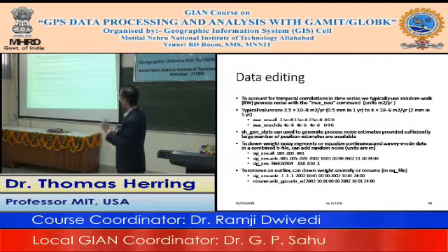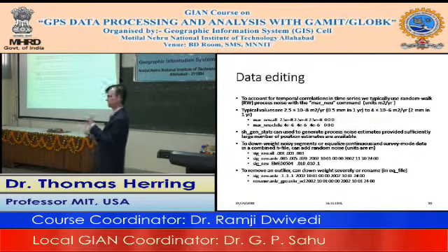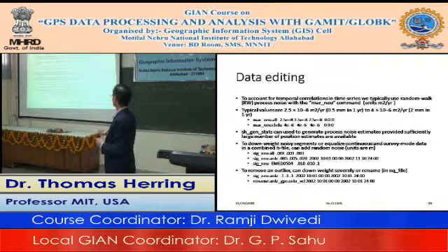So that's one way, is to downweight them by applying a variance to them. If you want to downweight a site completely, then you can just give it a really large uncertainty. And again, in terms of influence, it's always the ratio of this uncertainty to how well things are normally determined. A more preferable way, if you just want to get rid of the site completely, is to put it into the EQ file as a rename. We have this special syntax that renames a site to XCL at the end. And one thing I should have said earlier is that in GLOBK, the site names are 8 characters long, not 4.